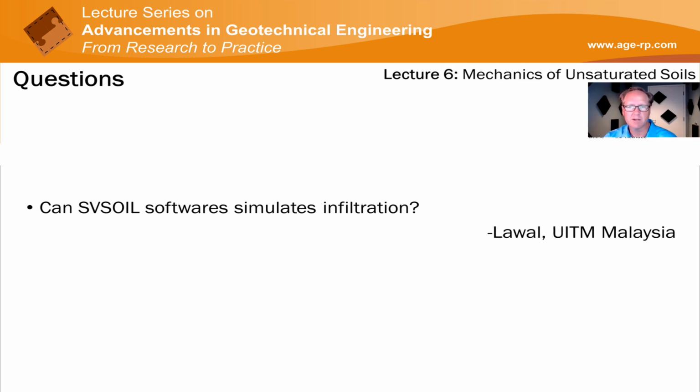And in Bentley, you can also use Plaxis with the shear strength reduction to do slope stability analysis as well. So to model infiltration very easily, use SV Flux. You can analyze that condition very easily, taking into account unsaturated soil mechanics and full climatic conditions, actual evaporation and everything with that.